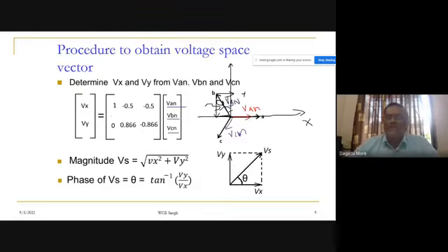Okay, this angle will be 30 degrees. So sine 30 is 0.5 VBN, and it is in the opposite direction, so this will be minus 0.5. We can get BN. Similarly, the CN we can resolve here. Whatever CN value we resolve, again this angle will be 30 degrees, and sine of 30 will again be 0.5, in the negative direction. So we resolve this along three components along the x-axis.